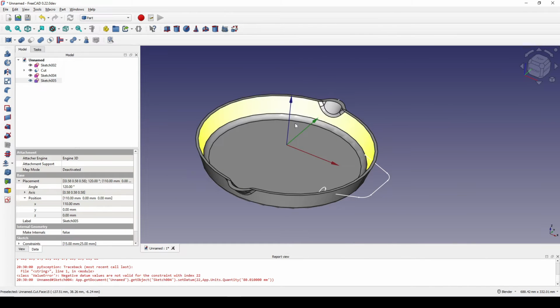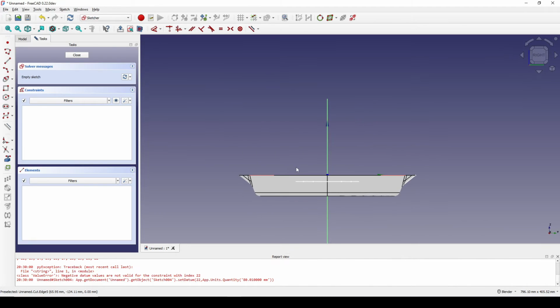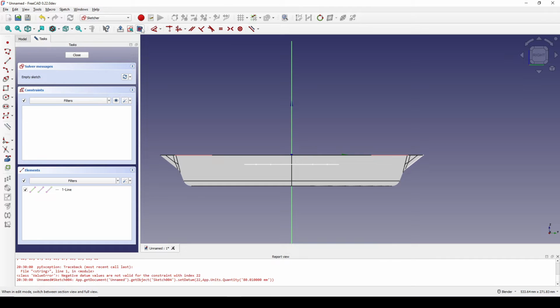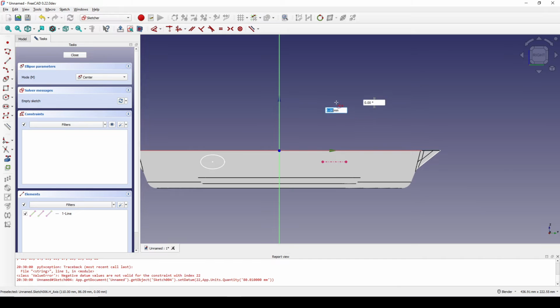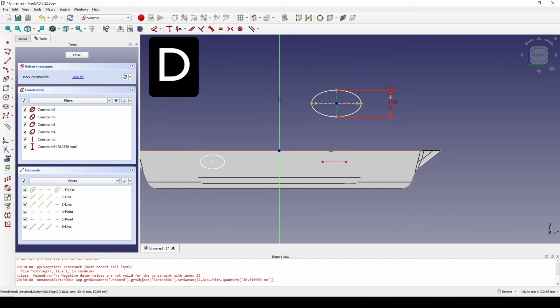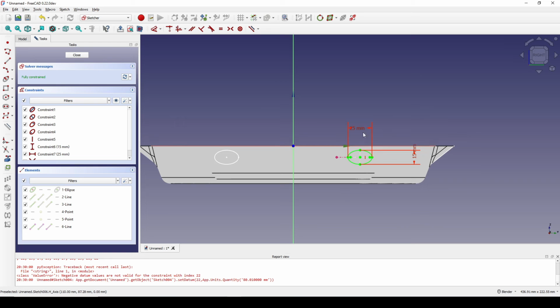Hit close. Doing the same, create another sketch on the right. Offset it to 110. And reference the line on the right. And view the section. I create an ellipse. Center. Select this line and hit V for vertical constraint. And hit D and set the distance. 15. This one, 25. Select this point and this point. Hit C to snap it. Now close.